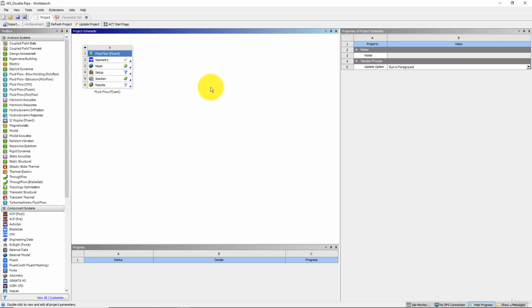All of these things can be done with a single click on this screen. All input parameters will be updated automatically, and all output parameters will be obtained from that simulation. You can define multiple design points and solve them in parallel if the license permits and you have enough CPU power and RAM. You can also run them in series, in which case it will take more time, same as running these cases one by one, but in an automatic fashion.